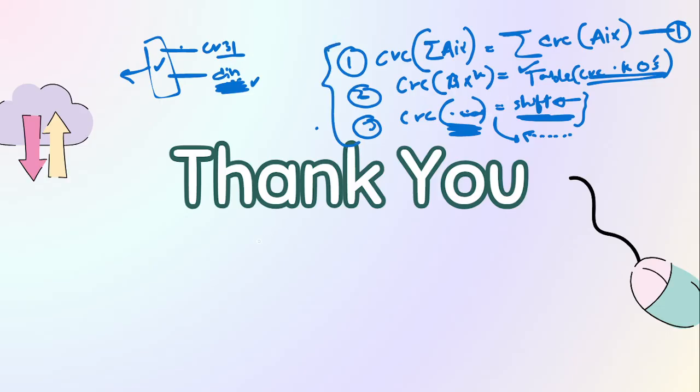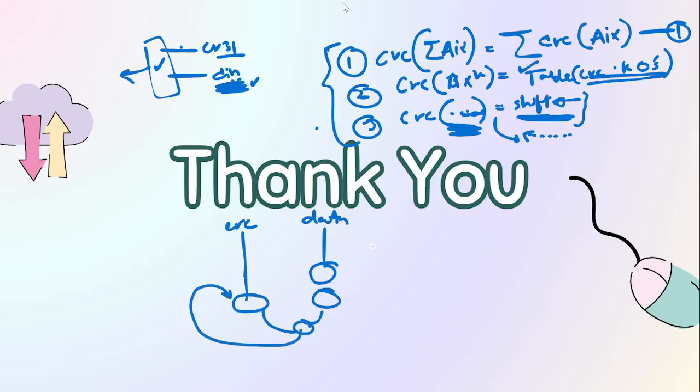We also showed a way of pipelining. So we showed you how to pipeline the CRC and data. So you had data, you had different stages of XORing, and then eventually you merged all these and then you feed it back onto the CRC. So we showed how to pipeline these efficiently. We showed this on both functions and tables, right? Because you can do this using functions that are available online, and you can do this using tables that I have showed you how to build.